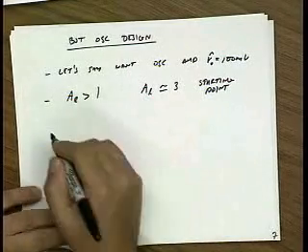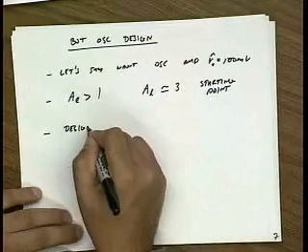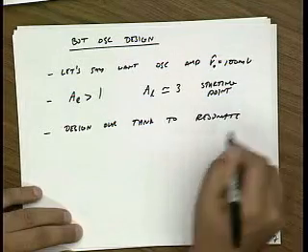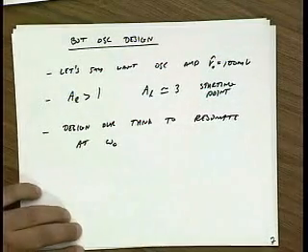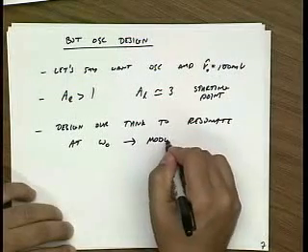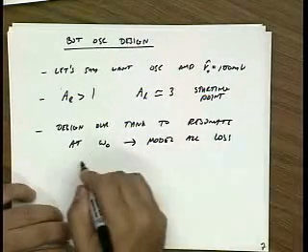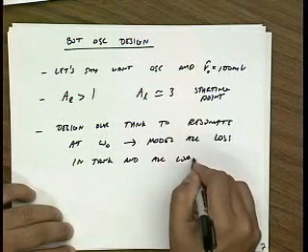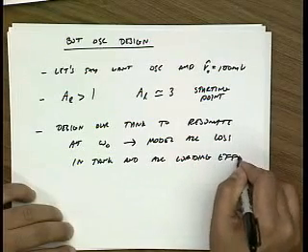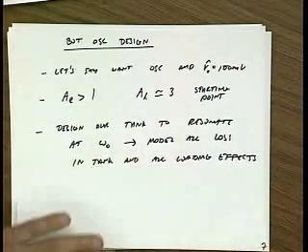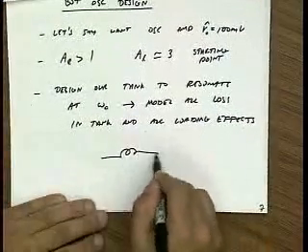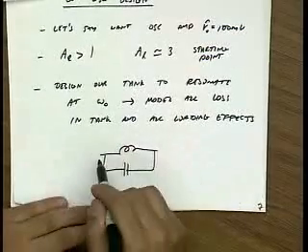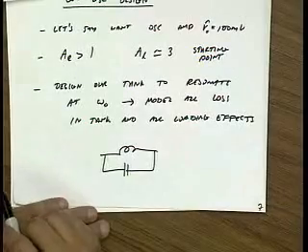Okay? So the next thing we do is we design our tank to resonate at omega naught. And here we have to be very careful to model all the loss in the tank and all the loading effects. The tank is something sacred. This is my LC tank, you want to keep it as clean as possible, so avoid putting anything on this tank that would de-Q it.